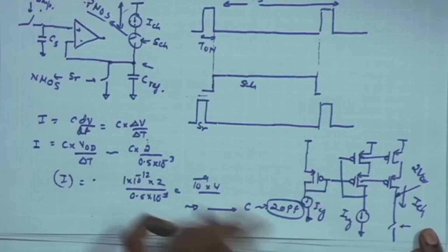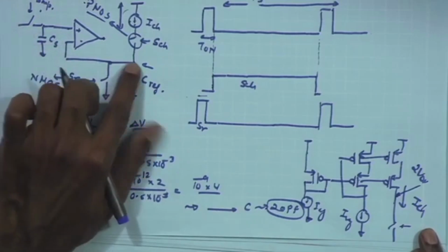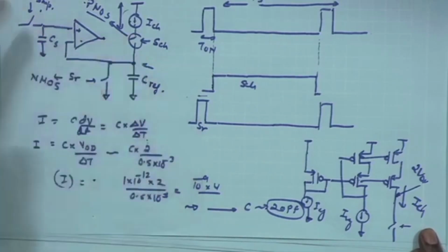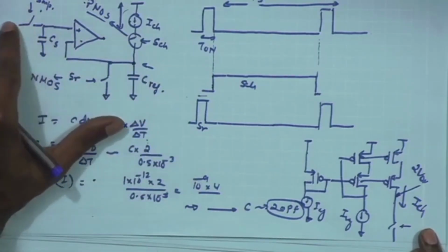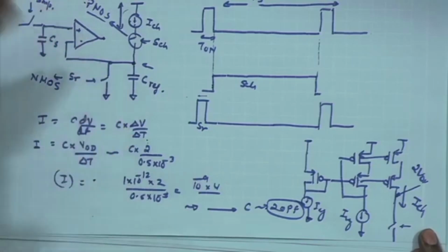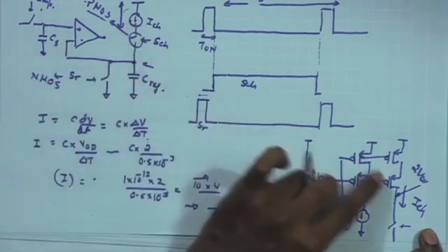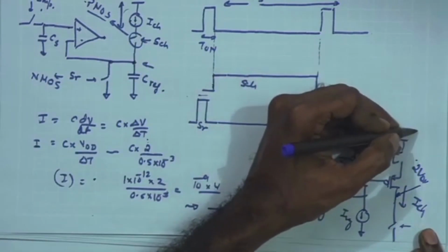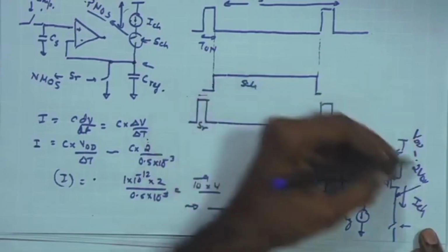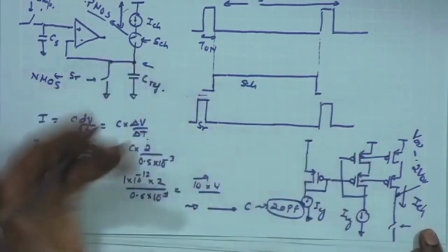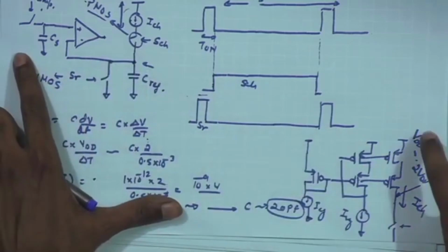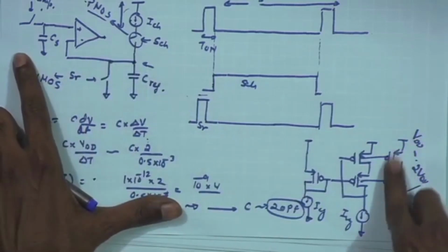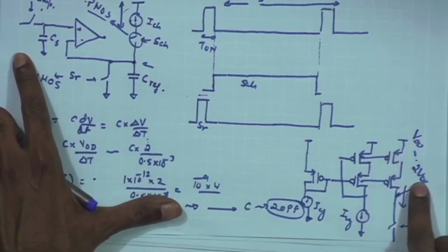We can also make sure that the maximum output over here, which is supposed to match the maximum output available from the amplifier, which is again VDD minus V overdrive of the previous stage, matches the maximum voltage that I am expecting at the input, by appropriately sizing these two transistors with sufficient W by L so that the V overdrive is minimized.